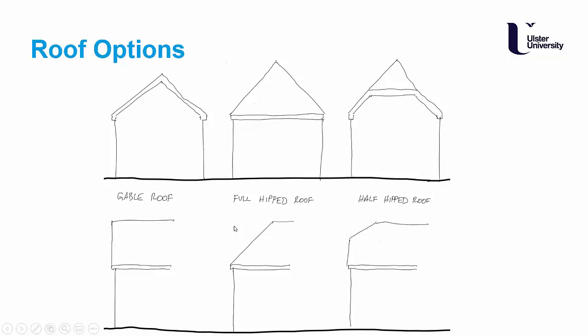A full hipped roof is different. So in this case, the roof changes from a wall to a roof at this point, and it's angled up at a 45-degree angle. So on the side, you will actually see a fascia right across at the same level as it is on the front and on the rear elevation. The roof height is still the same, but it's pitched back.